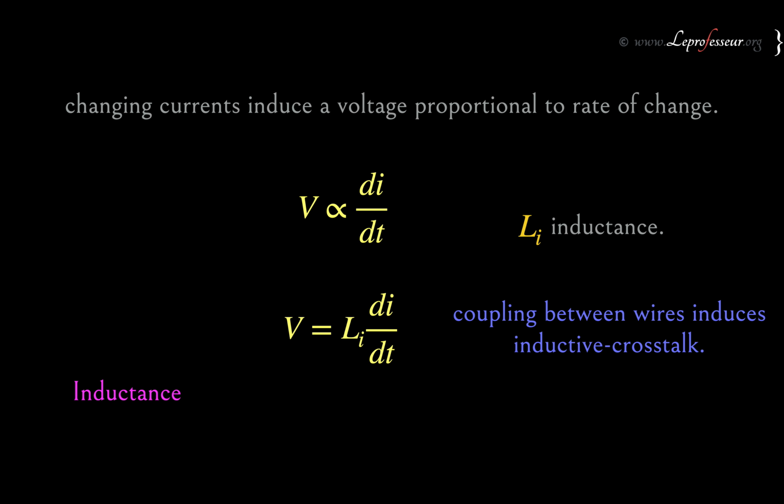That will induce inductance, and we would have inductive crosstalk. Crosstalk is a very notorious thing. It makes life more complex. Crosstalk analysis and fixing the crosstalk is one of the very important tasks in VLSI physical design.